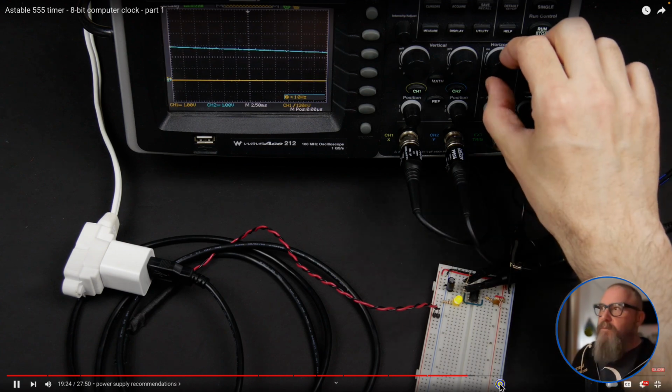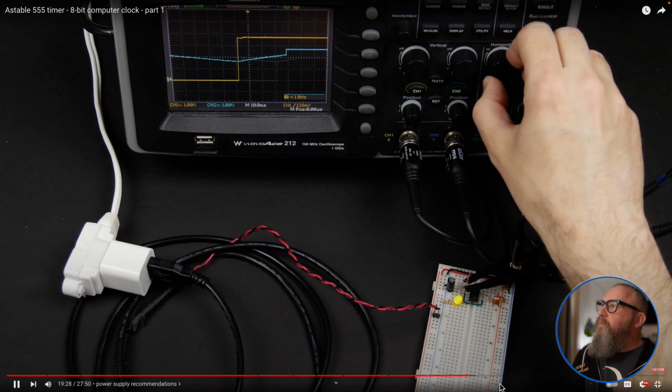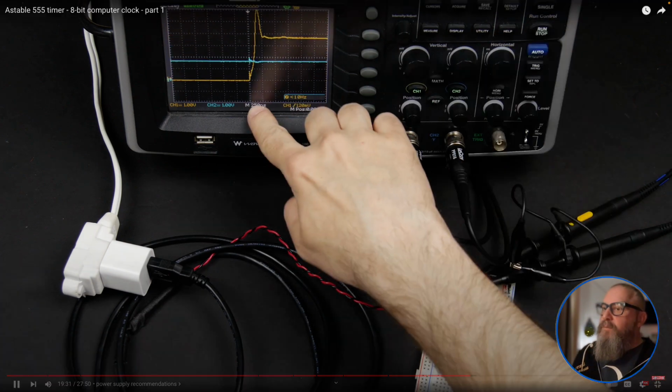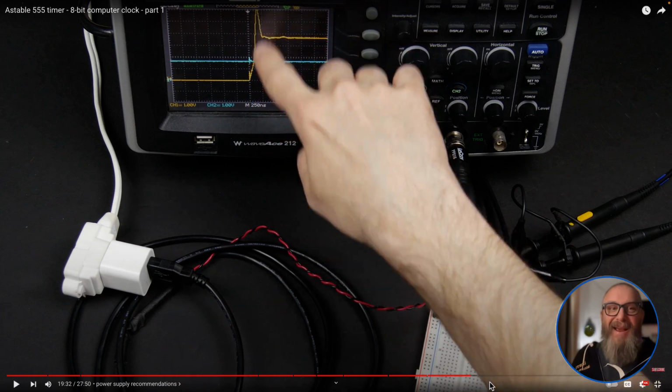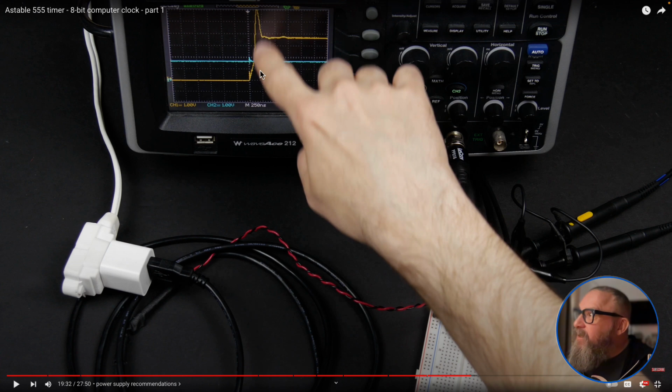There's still some other noise if we go in even further, oh, I'm going the wrong way, all the way into the nanosecond range. So this is why, when you overclock it, this is the kind of problem it has, right? The engineers have seen these issues, and they said, okay, for everything to settle back down, this time period between here and here, this settling period, really depends on how they've got these circuits set up. So they've measured it out. We'll be guaranteed good here, but what happens beyond that?